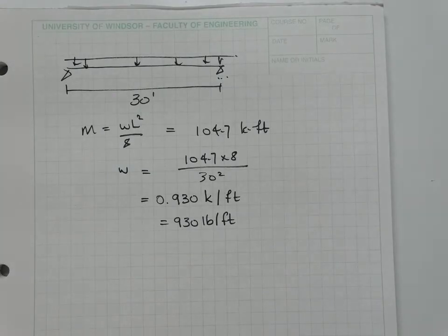That's not a very big capacity. If you figure that's, let's say that's 40 feet this direction. 40 feet times 1 foot width is 40 square feet multiplied by 50 pounds per square foot is 2,000. And cutting it in half, because half of it sheds the load this way, this beam has a requirement, unfactored, of sort of 1 kip per linear foot dead load. It's inadequate.